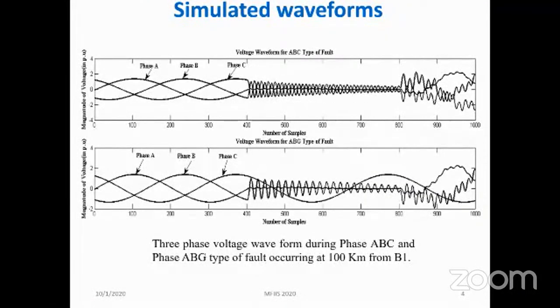And during any fault, it was observed that the line impedance of the affected phase falls below the value of the normal condition, and this is actually the case. But in the simulated relaying system, the line impedance of each phase during a fault condition was compared with that during normal condition. We will go to the block diagram of the relaying system in the later slides, but this is a brief introduction of the earlier work that was done.